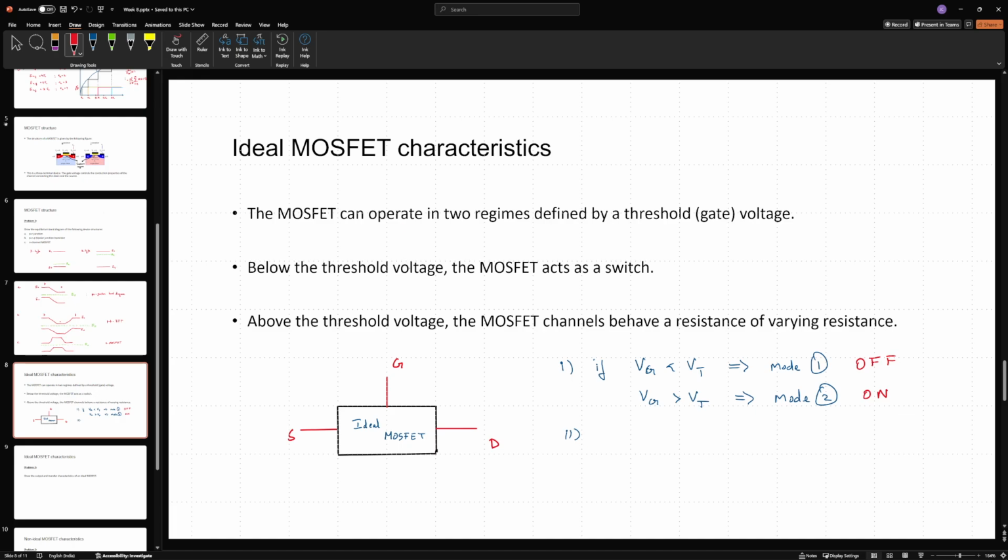Essentially, when I say below the threshold voltage, what I mean is moving above and below the threshold voltage. If I have a signal source that has a fluctuating or time varying voltage that is moving above and below Vt in some pattern, then my device will move from the on state to the off state corresponding to the value of the voltage coming from that signal source. So that is what I mean when I decide to take my MOSFET below the threshold voltage, I can use it as a switch.